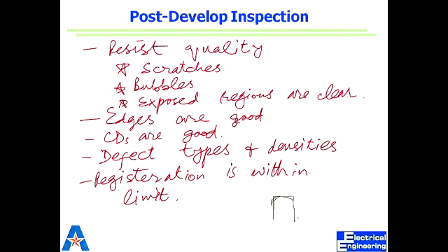Right? But for me, in that mask, I have a line. Smallest line is 3 micron wide, and that is my CD. But with that technology, with that light, with that mask, with that resist, I may be able to make even smaller than that. But for that mask, my CD is 3 microns. So I have to know where to look for it. So I'll go looking for, scanning for that smallest feature I had. So if that comes out good, yeah, that gives lots of comfort that the bigger one would have come out good.